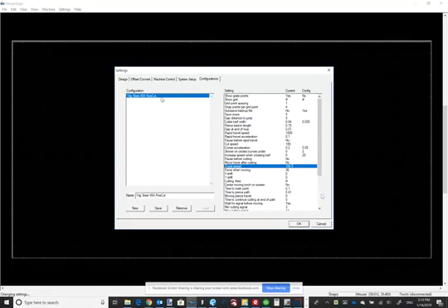But advanced machine control gives you the ability to save. You can have as many of these over here as you want, and it lets you save all of your settings as a different file name that you can reload later. So if you have a setting, for instance, for 14 gauge, 45 amp fine cut mild steel, I might have the same thing for stainless steel with that amperage and consumable, or different thicknesses or different consumables. So you can have all of your presets there.